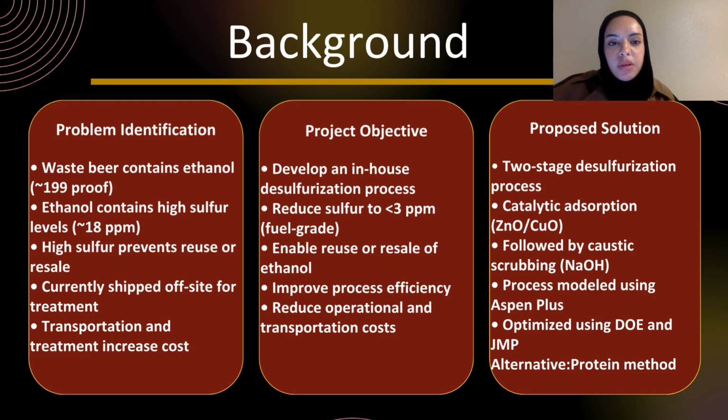For our proposed solution, a two-stage desulfurization process, catalytic adsorption followed by caustic scrubbing, was modeled using Aspen and optimized using DOE and JMP. Our alternative solution was the protein method, which Anis will cover.